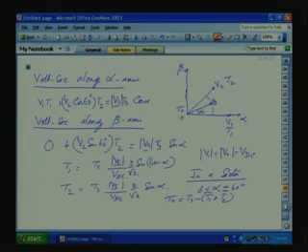Inverter switching always has switching losses associated with it, because switchings are not instantaneous. So we want to ensure minimum switchings during a transition, as it goes from 0 to V1 to V2. These are called sub intervals. That means T1, T2, T0 are called sub intervals, the intervals within a period Ts. So during the sub intervals we want minimum inverter switching.